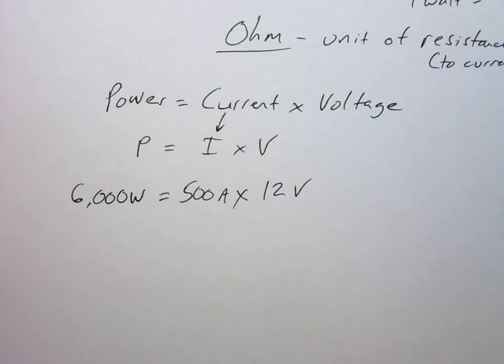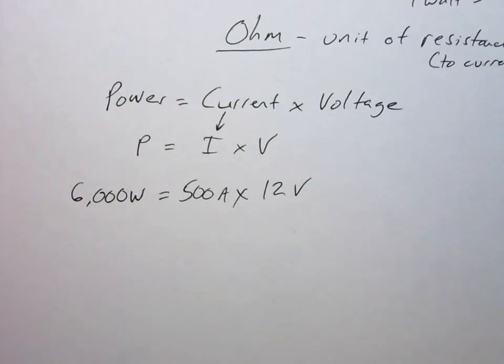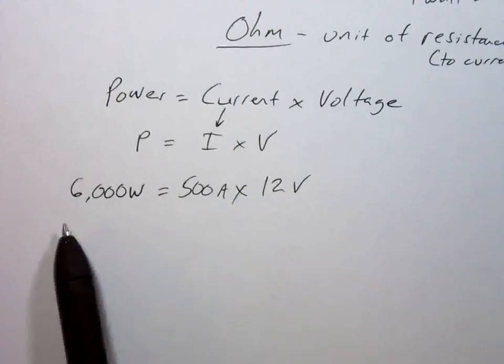In a diesel engine, you have to force and create enough compression to get the diesel to the flash point where it basically explodes under the pressure. So you have to be able to crank with a lot more power. So there'd be 1,000 amps or more supplied from diesel batteries to start that truck. It's incredible. And of course, that would translate to 12,000 watts.